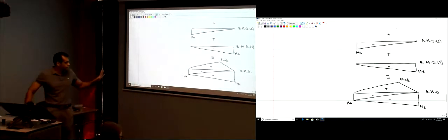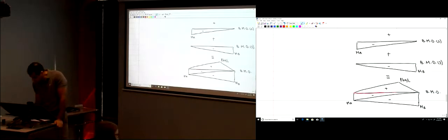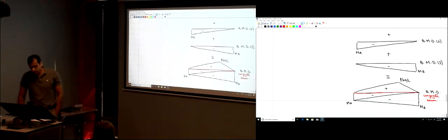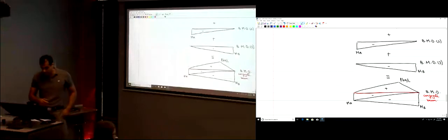So now I have those 3 parts. This is the bending moment diagram. All I have to do is put this on the conjugate beam. So this is the conjugate beam in red. How would the conjugate beam look like? The real beam is fixed, so the conjugate beam is free, right? Free beam. Now, assume this bending moment diagram is now load on the conjugate beam. I need to concentrate it into some concentrated forces. So now I'm going to divide it into 4 parts.